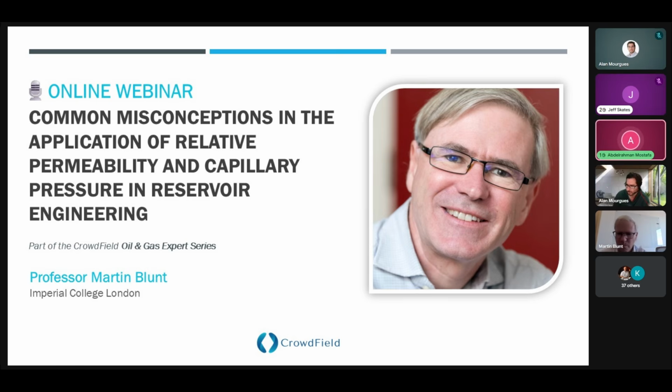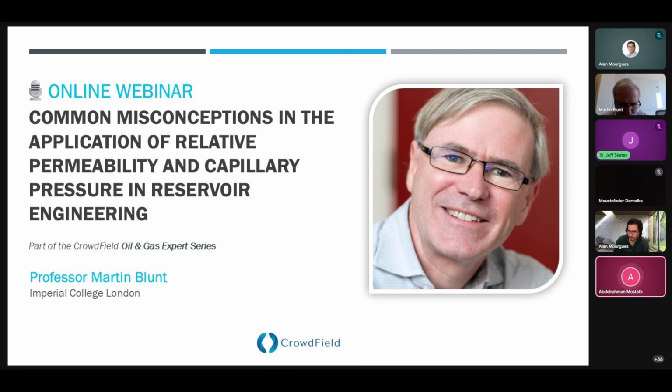Yes, hello everyone. I have a question regarding the production from the field. As I see from many fields, we are using the primary drainage curves in the initialization of water saturation. But with production, most of our fields, even if they contain a weak aquifer, the saturation of oil decreases and the saturation of water increases with time. So that can mean natural or spontaneous imbibition.